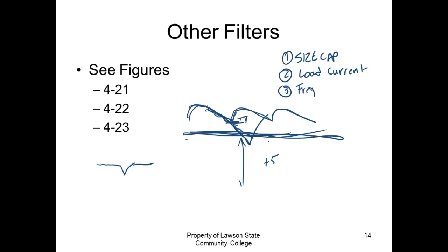So that's why it's very important to choose the right size capacitor for the current or the load that you're trying to drive. Now the problem is, you say, why don't I just go out and get a 50,000 microfarad capacitor? Well, a 50,000 microfarad capacitor is probably going to cost you $30, when you need a 1,000 microfarad capacitor, which you could probably get for $2. So if you design power supplies and put a capacitor in there that's too big, you're wasting a lot of money.